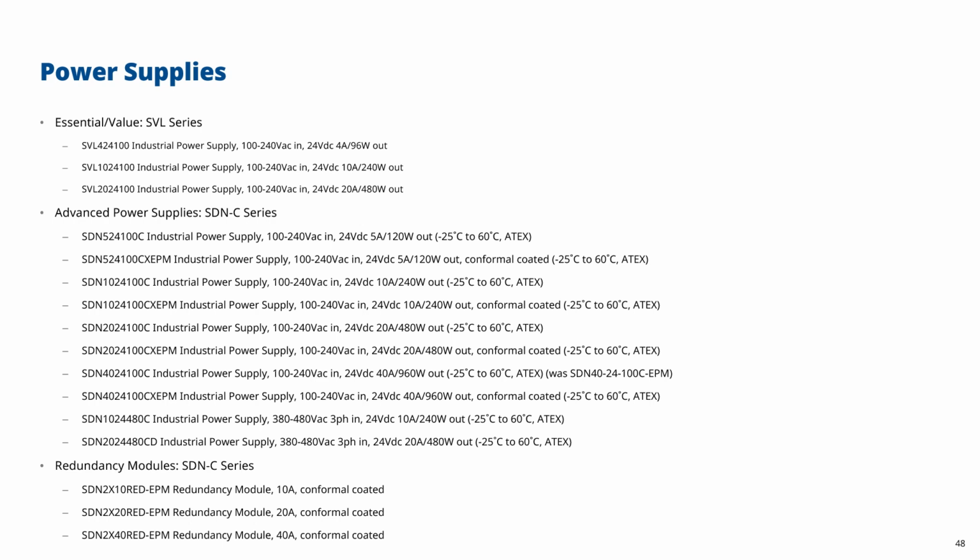So that's what you use typically for I/O. You would use a redundancy module along with 2 power supplies to give you your I/O supply. For redundant PLCs, I wouldn't use a redundancy module. I would just use a separate power supply for each CPU and do it that way. So that saves you a bit of cost and it also simplifies the wiring. And of course, that also fits in with the redundancy scheme.